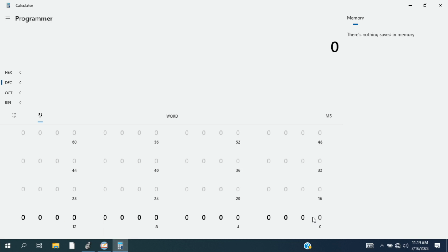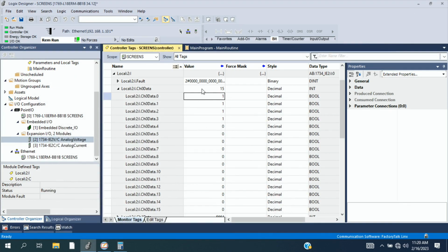So if I wanted an expression in binary of a number, let's say, let's go with 36, okay? Well, I'm going to need to have 4 added to that. So again, 1s, 2s, 4s, 8s, 16, 32. So 32 plus this 4 is going to give me 36. This programming calculator is useful for you guys just to experiment with and see how binary numbers and integers work. But as you can see, it's 16 bits that stores that number in our analog input.